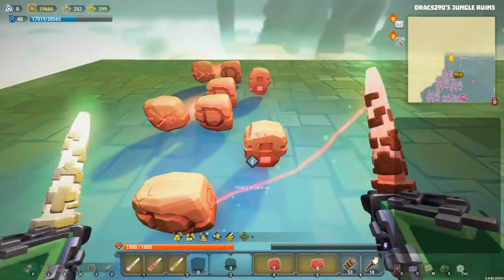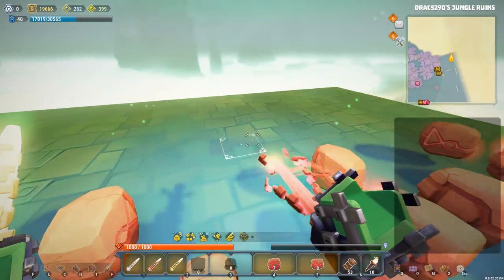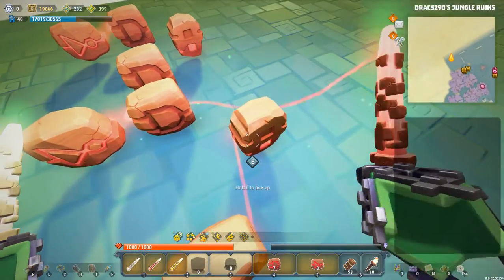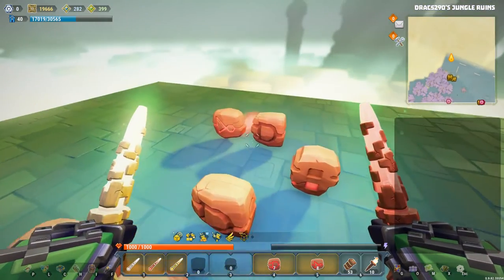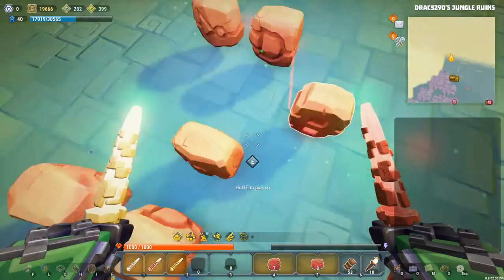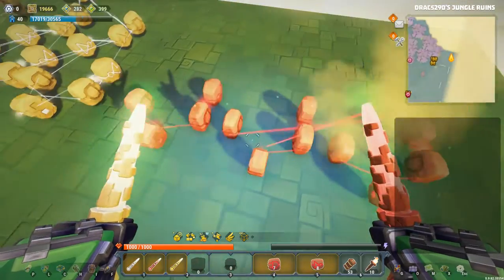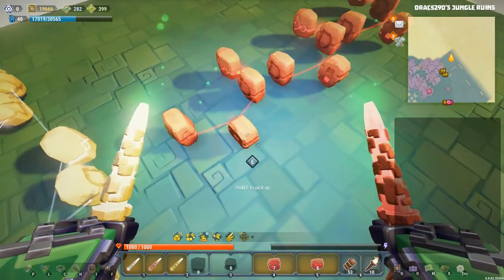So no NOT gate goes into the on side, and the AND gate for the NOT gate goes into the off, just like that. And same again down here. So the one with the NOT gate goes into the off side, one without goes into the on, just like that. Now we can hook up the lines between the latch and everything else.